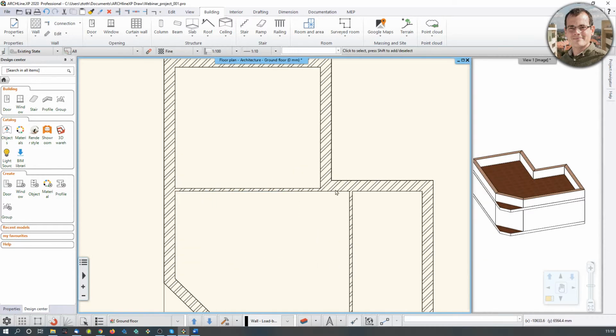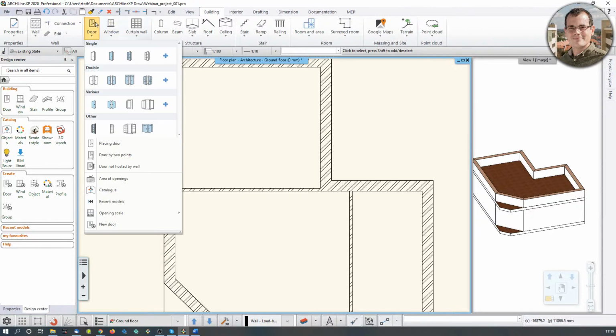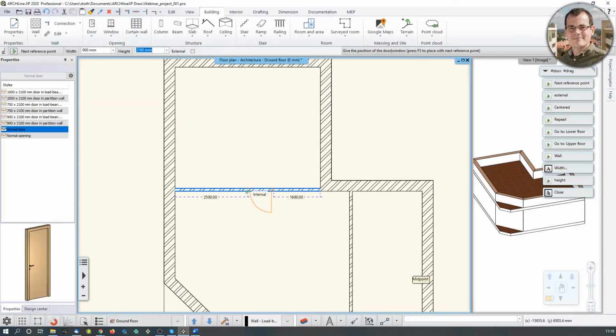And this is where I want to position it to, but I don't know where I want to position it from. So how do we do that? I click on the door icon and hover my mouse over the wall, and now this green node appears, and the green node tells me that currently my door is going to be 1420 millimeters from the corner on the right.